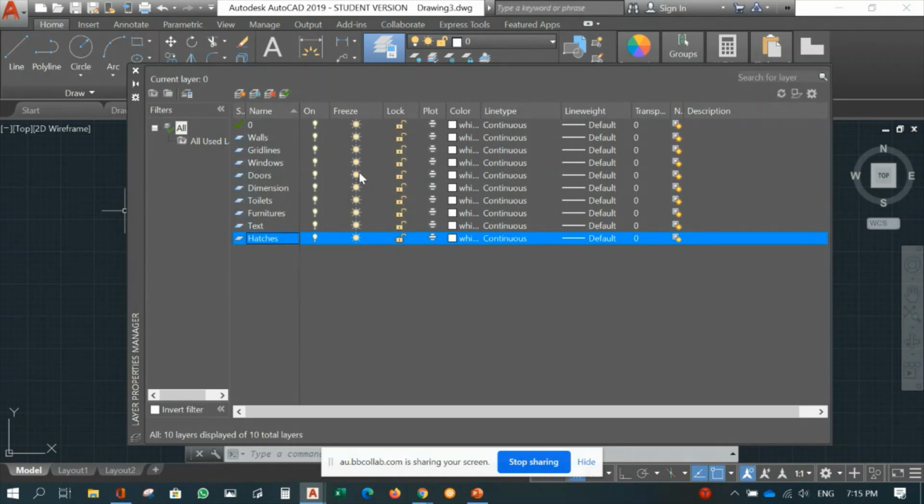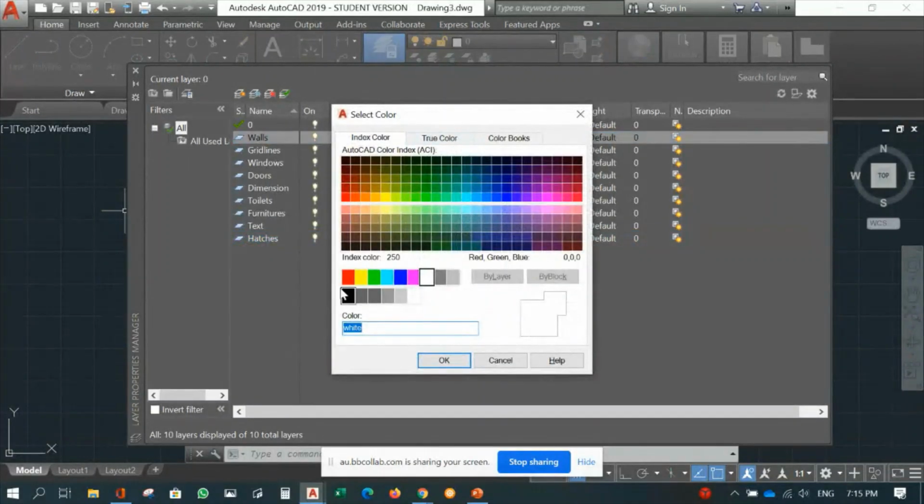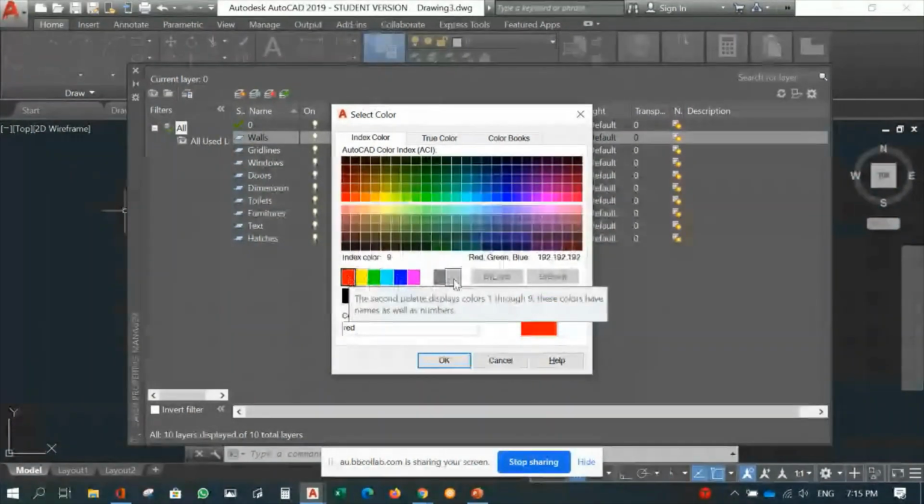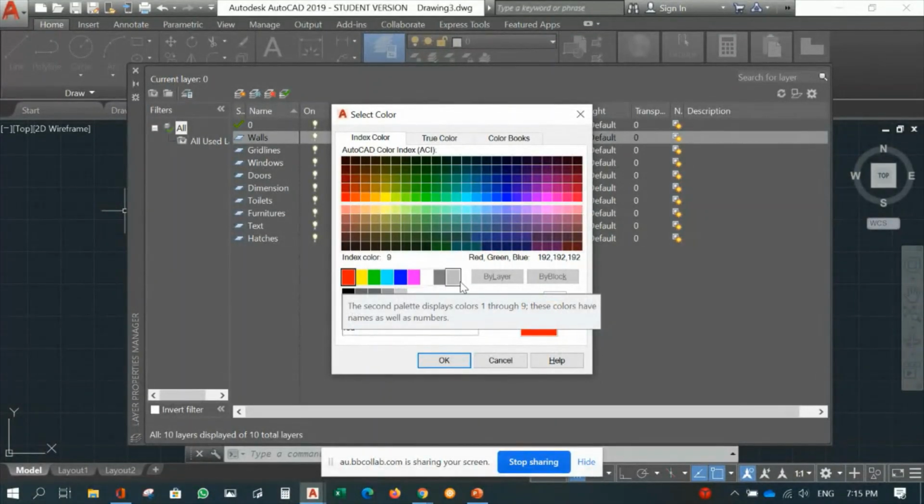So how do we separate these? By applying colors. For walls, we always apply red. So, colors in layers, or we say colors in technical drawing. Please use colors from 0 to 9 here. They are separated here on purpose, so please use them. Why? Because all these 0 to 9 colors refer to 0 to 9 pen thicknesses.